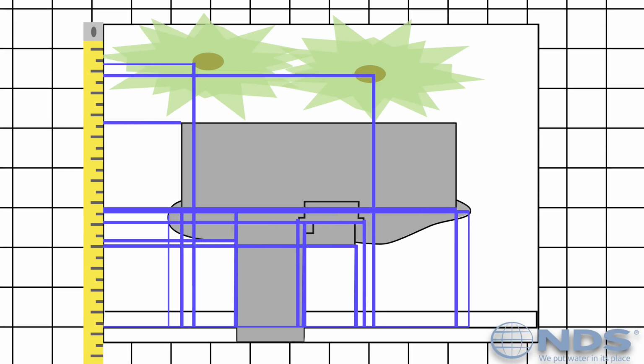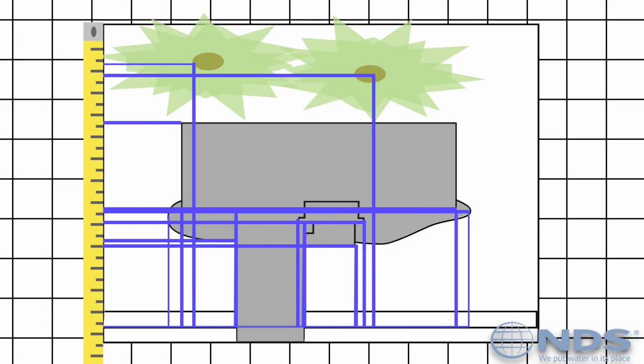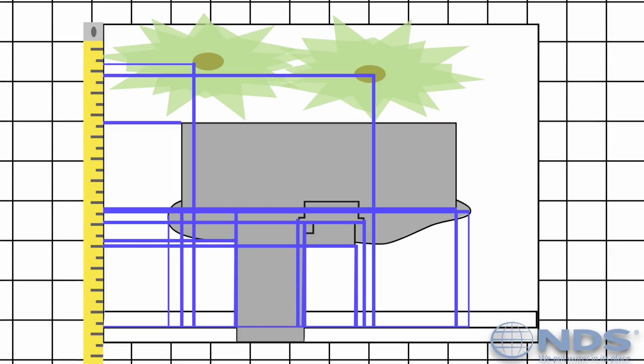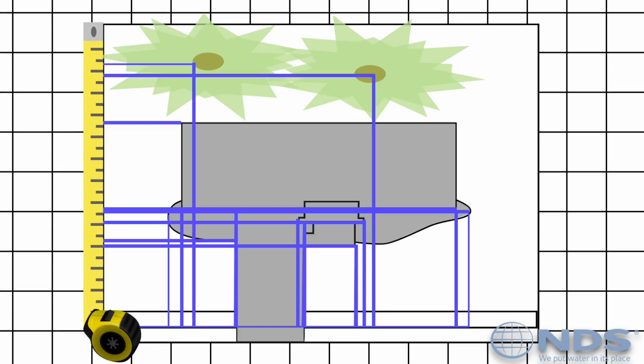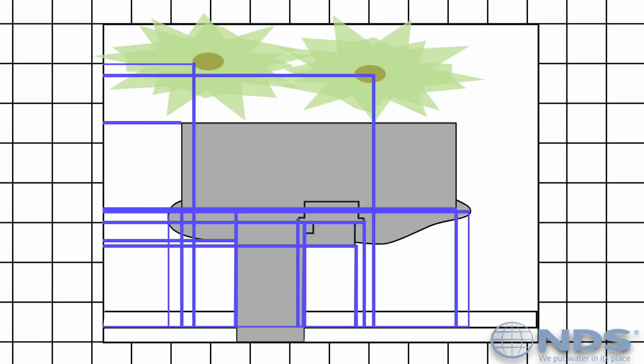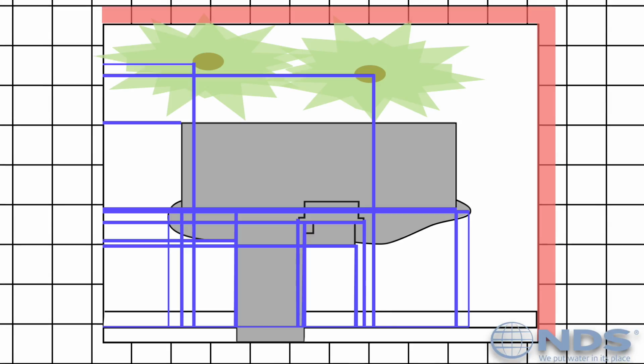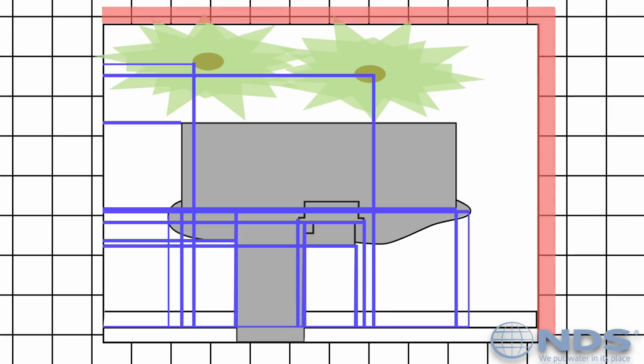You'll now have 2 coordinates for everything on the property, and you'll be able to easily draw the property to scale on your graph paper as you go. For houses with complex back or side yards, you might need to repeat the process along the back edge of the property and on the other side, but 2 passes are sufficient for most properties.